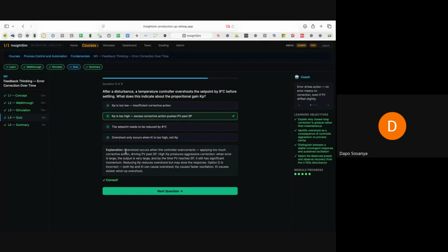We'll discuss the features of a valve in the course we're starting next week. So there is wear and tear in the valve trim, and it has left some allowances, and then the lag time of your process has changed. Maybe it has increased, and then the tuning you did last quarter or last year does not apply anymore to the condition of the process now.